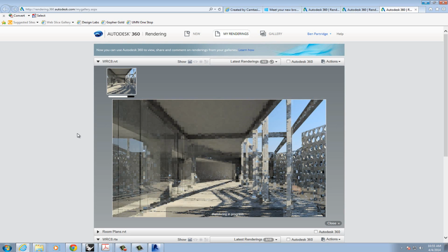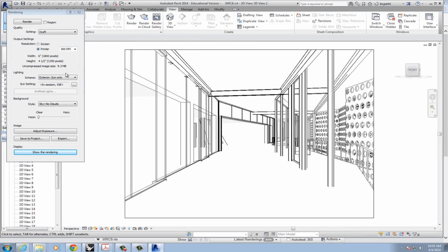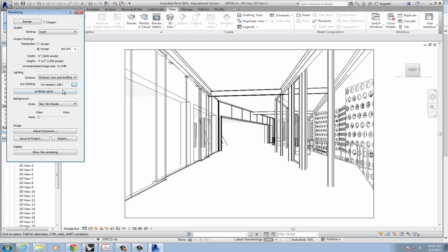Revit's lighting photometric capabilities, like the lumens that you put in for your lighting, are not always accurate, and that comes down to the fact that it's a biased renderer. Biased meaning that we've limited it by calculations. Unless we tell it not to limit by the calculations, it's going to be a little bit inaccurate versus using an unbiased renderer, which would be 100% accurate but take a little longer.